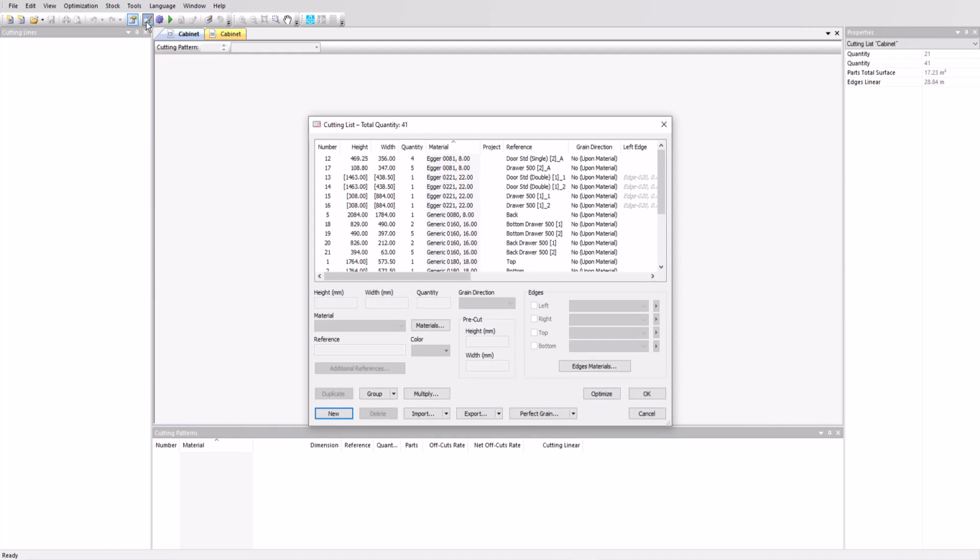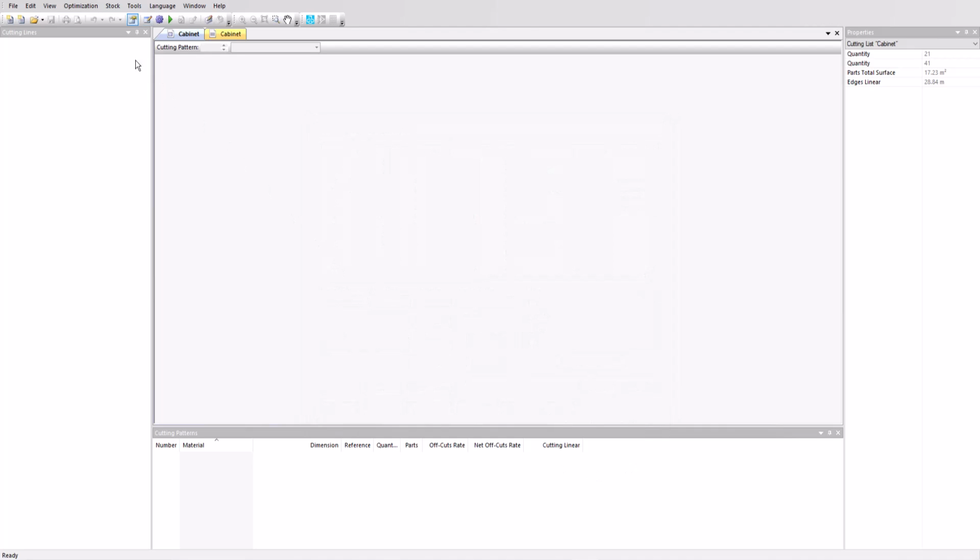This window shows a list of all the parts that require cutting from our panel stock. As alternatives to the PolyBoard integration, the cutting list can be imported from a spreadsheet here, or you can select the New button and individually add parts. Our materials and stock of panels and bars is already set up. The materials in fact are synchronized with PolyBoards. However, as with the cutting list, new materials and a stock of those materials can be added individually or imported.